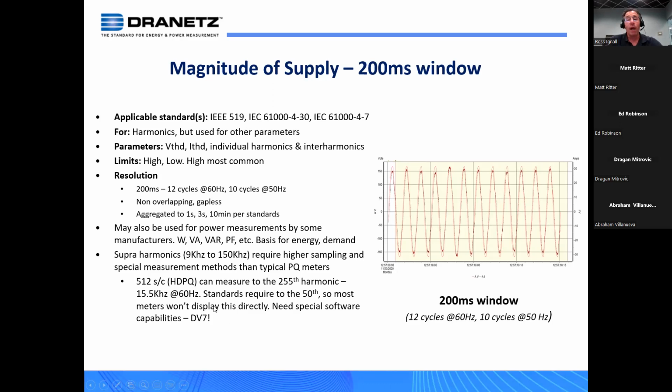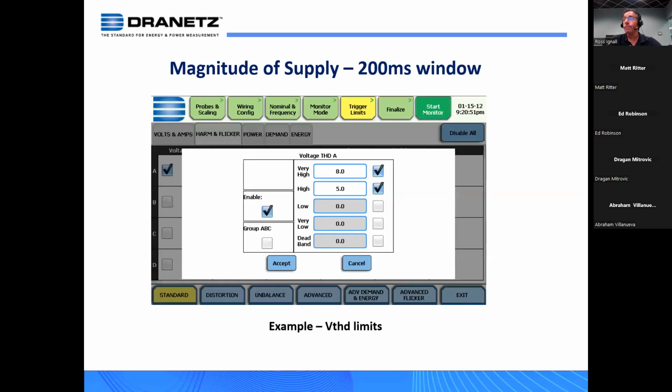But the harmonic and time plot calculator of Dran-View, a standard capability of Dran-View 7 Enterprise, can do that for you. An example of doing that is the G55 standard in the UK, which required going up to the 100th harmonic. They doubled it in the newer G55 standard released over the last few years. So the solution for our customers was to use Dran-View 7 Enterprise to pull that information that their meters already had, that they've been using for years.